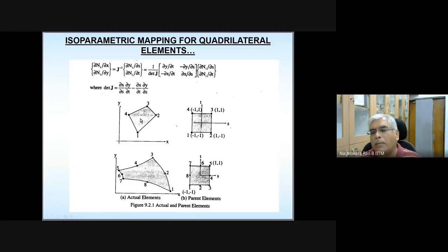In case of 1-dimensional problems, we already looked at this kind of thing. We plotted the Jacobian, and then we saw whether the Jacobian is always positive or not. But here we cannot simply plot. It's a 2-dimensional case, so here also we can do plotting, but that plotting is going to be a little bit more involved. So that we will see. It's not simply checking whether J is above the datum line or not, because it's a matrix here. Please take a note of this.